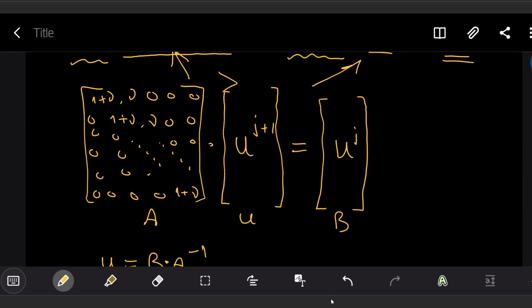From another point of view, you need to obtain your solution as soon as possible, so you cannot keep a very low Courant number. If you keep it low, it will be super stable, but it will take a very, very long time to solve, basically a huge simulation time, which we cannot have.